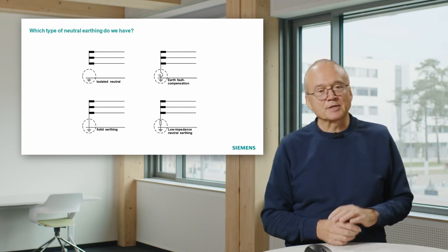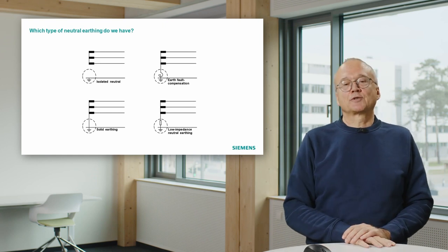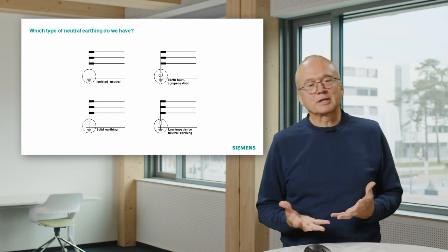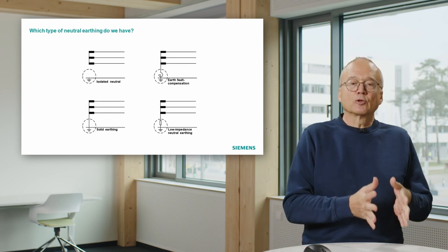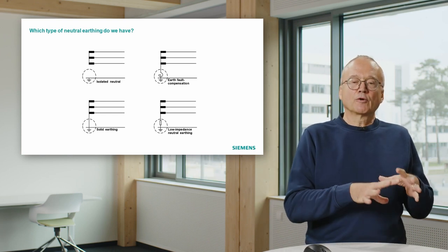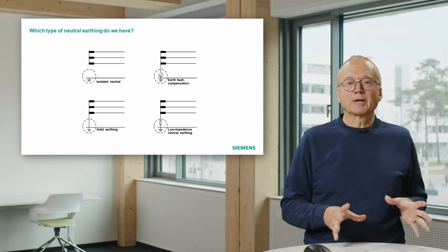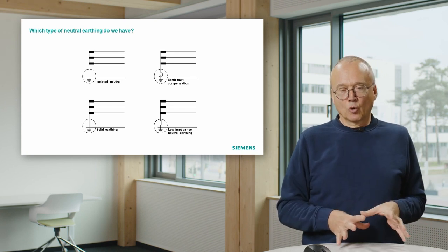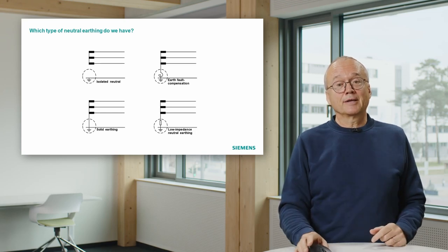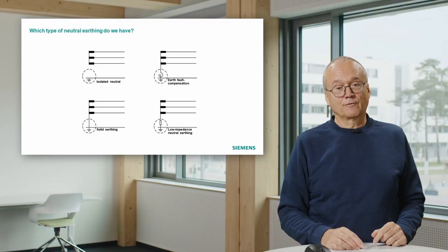And for some cases, especially in distribution systems, this is done. Because for the most probable type of fault, you have then a reduced short circuit current, which means the risk of damage, of injury of people, and so on is lower. But that refers only to phase-to-ground fault. That does not influence the short circuit current in case of a phase-to-phase fault.